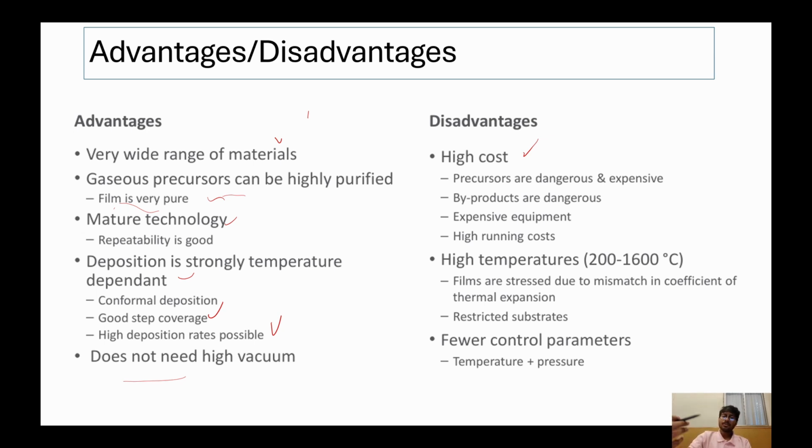We use them. And byproducts are dangerous. We need to contain the byproducts, and after the pump we should have some kind of scrubber unit for these kinds of dangerous gases. They can reduce or oxidize these gases, and then release them to the environment.